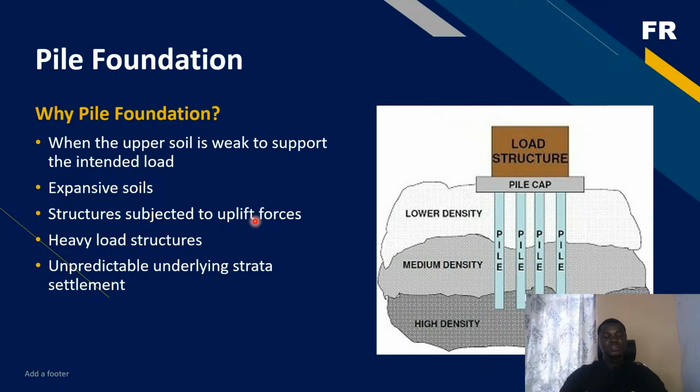So if you design those kinds of structures with a shallow foundation, even though it works structurally, this foundation can be exposed to erosion and a lot of environmental issues. So the best foundation you can use to support heavy structures are piles, deep foundations.